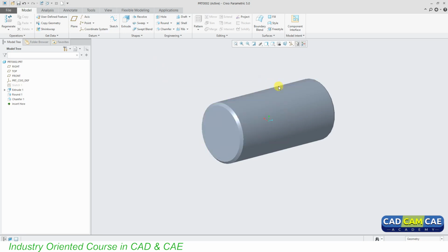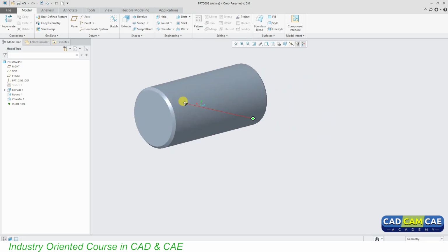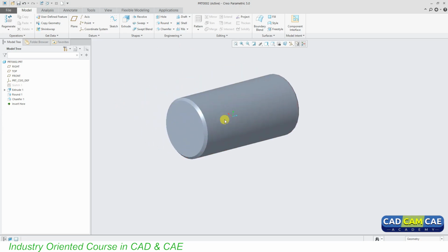Like let's say someone has to create cylinders of different shapes and different dimensions repetitively, which need to be used for assembling purposes. For that case, you can create the UDF feature, and you can just read that feature whenever we want to create this particular object for the subsequent assembly or during the modeling.